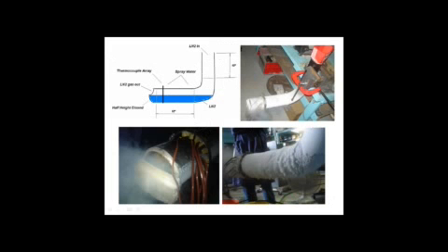Next slide. This is a condition where you'll see interesting developments in tight piping systems, and this was with catch tanks, cryogenic systems, systems when they drain, some flare lines that will build up either sludge or liquid on the bottom and then have a hot gas blow over the top, sometimes solar heating, sometimes rain on refractory lined pipes. What happens is you get a buildup of something in the bottom and something else on the top, so you get a circumferential heating pattern and bowing.